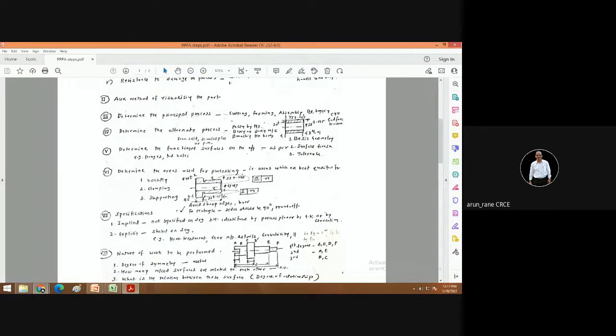Another is the third. What is the third criterion? Based on the tolerance. See, first was geometry. Geometry means squareness, perpendicularity, angularity, concentricity, parallelism. These are called based on the geometry. Surface finish means three triangles, four triangles, two triangles. Tolerance means, like suppose a bore is to be finished, we need tolerance. Without tolerance, we cannot work, isn't it? There is nothing like 0, 0. I cannot say that the size of this bore is 25.0. Neither can you measure 25.00, nor can I measure.